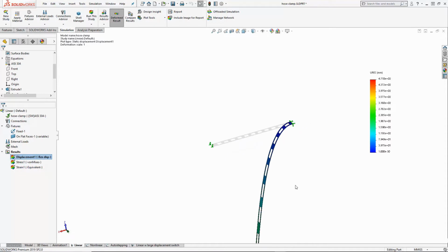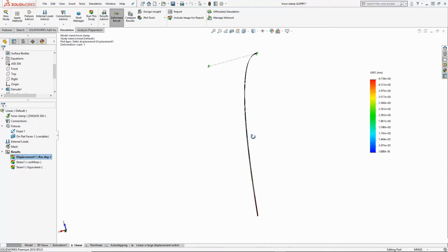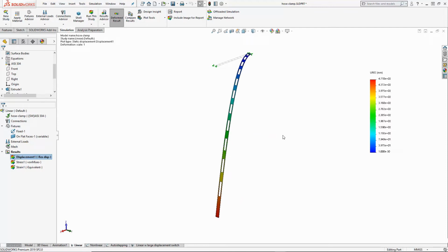And this has a deformation scale of 1. So this is the true scale calculated into this long shape. What's going on? There's no way that that turned around 360 or that that's the shape I meant to make. Well, remember, those loading directions really don't change. So while I told this thing to rotate, it really just kept moving straight down here. Just like if I put a force on the end of a diving board, but never moved those arrows. So you just went straight down. So that's not going to work at all.